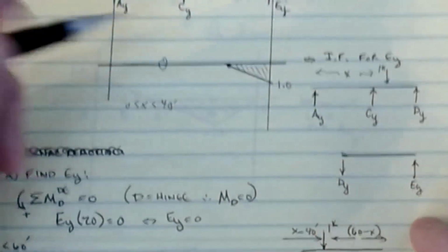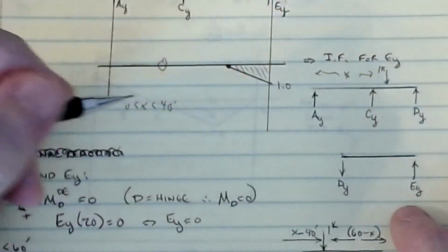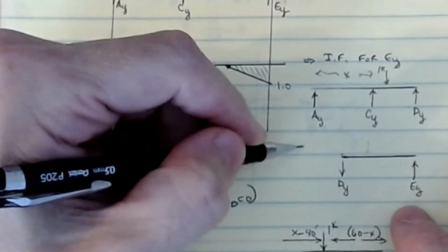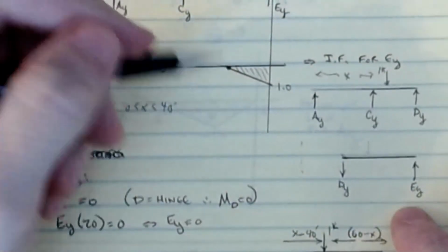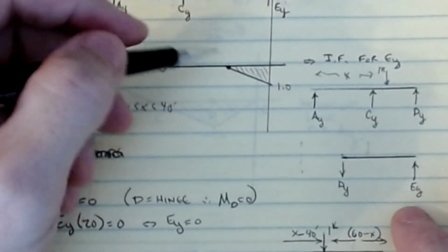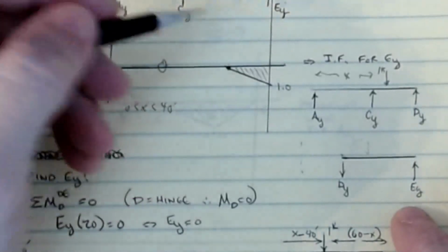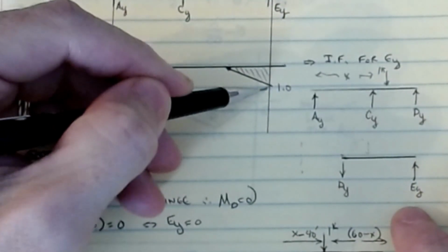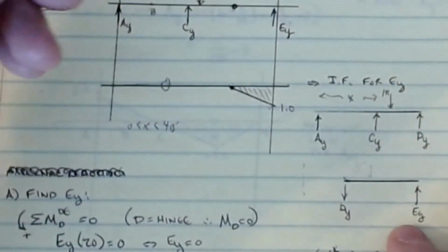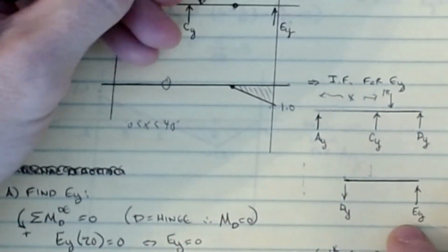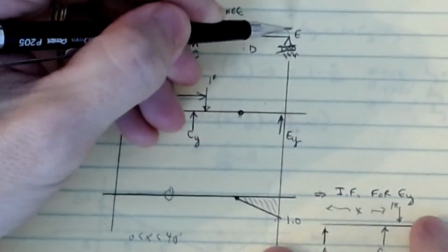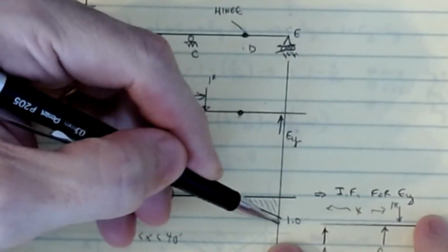Okay. And then we could go in and we could look at the other piece, which would be the case where now I put a 1 kip load on this guy, and I measure back to A, and you can build just like what we did in the last cantilever thing, that it would look something kind of like this for the reaction at E. Okay, now, when I do that, you find out that EY is a 1.0. And that's interesting because, again, the idea is that if I put a point load over this support, say the 1 kip load is sitting here, over the support at E, then all that load is going to go into E. It should be a 1.0.